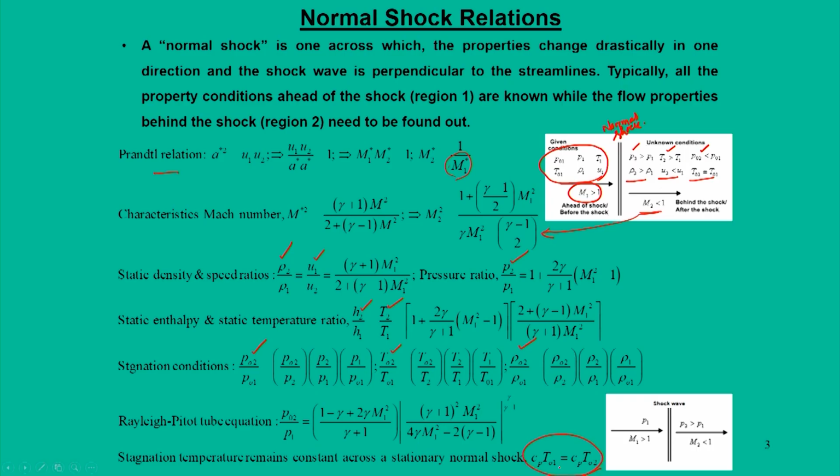Another important piece of information that talks about a normal shock is the Rayleigh-Pitot equation. This is one of the important equations which is used for experiments in a supersonic flow when we take measurements using a Pitot tube. So, this is the summary.